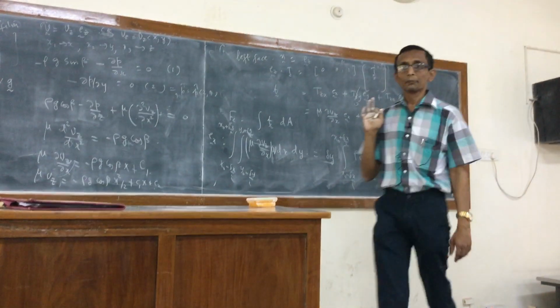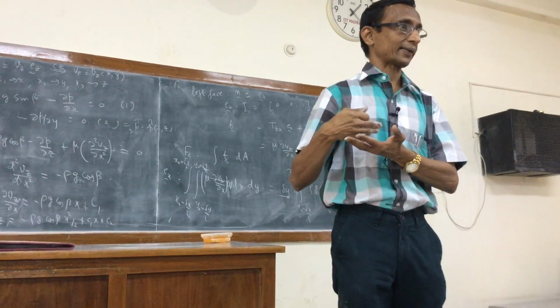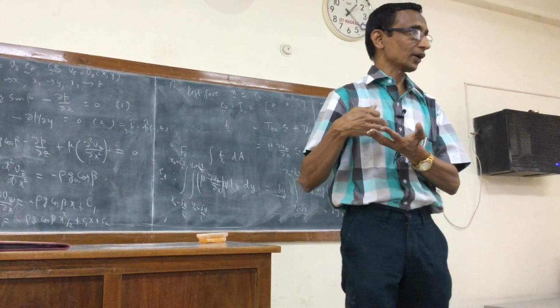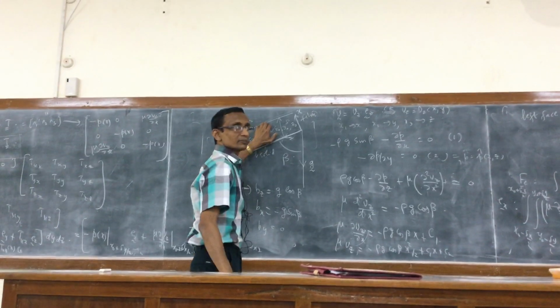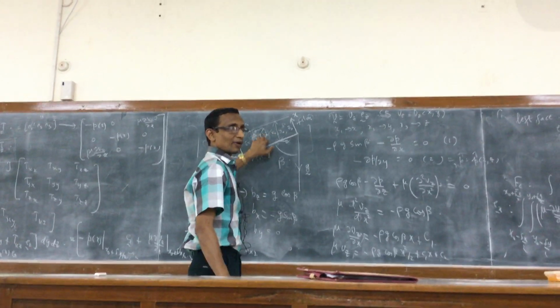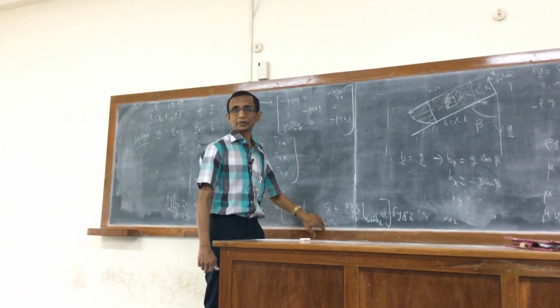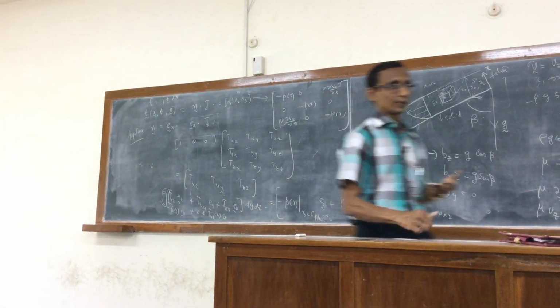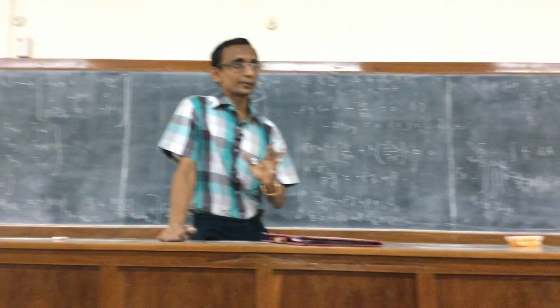Now for p, that also has to be integrated, because that's also a function of x. Wherever you have the top and bottom faces, the x value is the same. The top face, the x value is x0 plus delta x by 2. The bottom face, the x is x0 minus delta x by 2. For all other cases, you have to integrate.